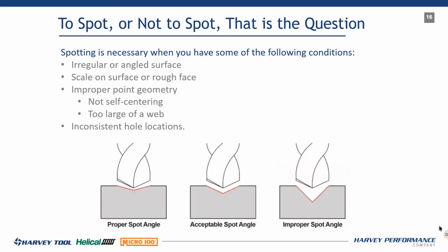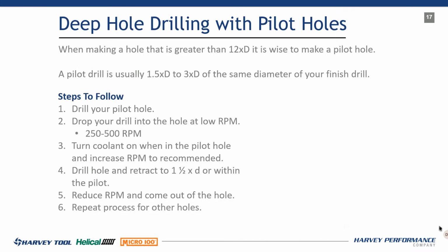So that being said, can you drill with a 90-degree and go in with a 140-degree drill because you want the 90-degree chamfer left on there? Absolutely. Are you going to run into problems long-term? Yes, it's all about long-term, right? We're drilling 1 or 2 holes. Man, I'll tell you what, go to your toolbox, open it up, find out what drill you got in there, put it in, and drill your hole. I get it. We all get it. We all understand it. But if you're trying to get in a production environment, you want to go with a flatter spot than you're actually using.